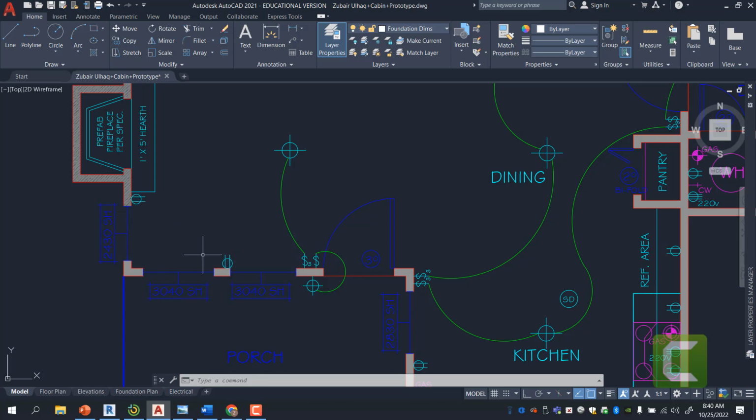So let's say if I have an outlet here, I can go 6 feet this way, 6 feet that way, or maximum 12 feet in one direction to have the next outlet. The idea being every appliance, everything that you have, comes with either a 3-foot or a 6-foot cord. So ideally in a bedroom type situation, the longest distance between your two outlets should be 6 feet.